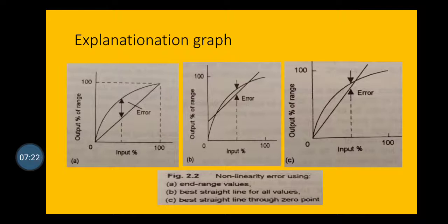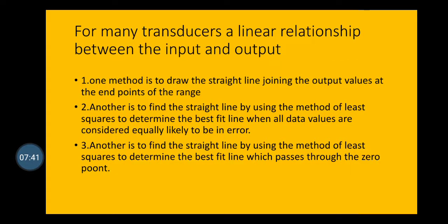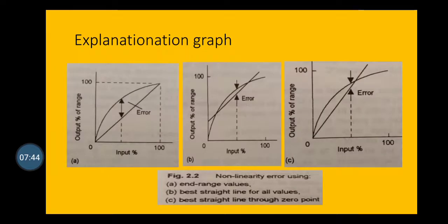The error is defined as the maximum difference from the straight line. Various methods are used for numerical expression of the non-linearity errors. The difference occurs in determining the straight line relationship against which the error is specified.